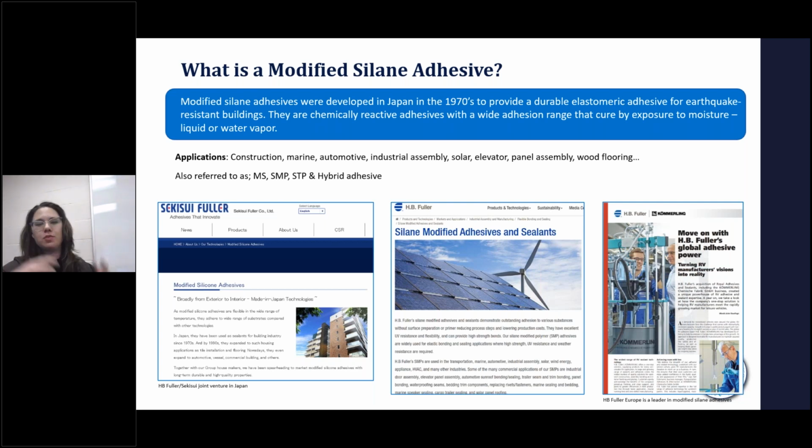So if you're in a high humidity environment, this adhesive will actually automatically on its own start reacting with that moisture in the air, and that's what's going to give you that final cure, which is the opposite of, say, a mastic. Mastics, you need the moisture to leave. With these MS adhesives, you want to bring the moisture in so that they can start to react, all right?